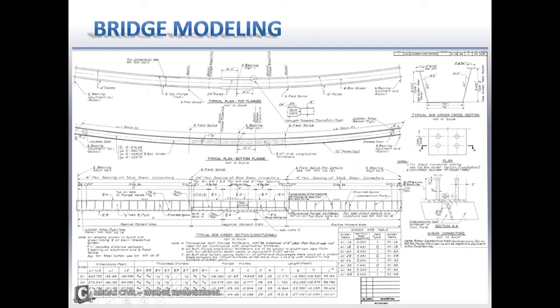Also where the longitudinal stiffener is, that also has to be separated from all of the other sections. So you're going to want to know all of the distances separately, and each girder is going to be split into different sections because MIDAS doesn't let you create one huge girder with different thicknesses and widths all along. So what we'll do is make a bunch of different girders and join them into one.